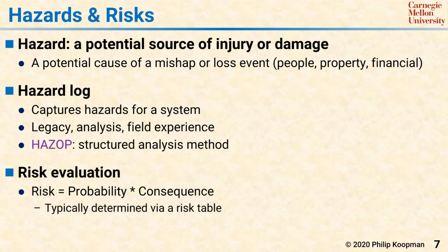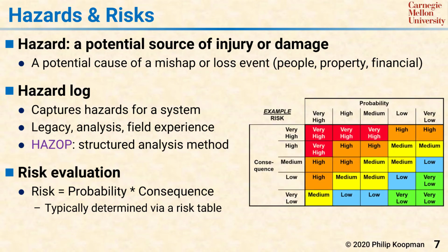Thus, it is common to see a risk table approach as shown by this figure. With the risk table, consequences are placed into perhaps a handful of bins, with each bin covering more or less an order of magnitude in severity. Any consequence on the border of a bin is rounded up to the next most severe bin. Thus, consequences form the rows of the table.